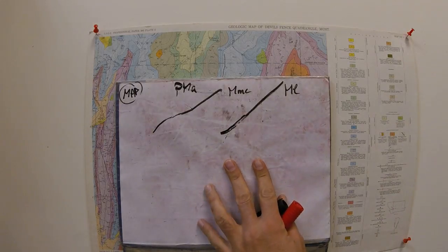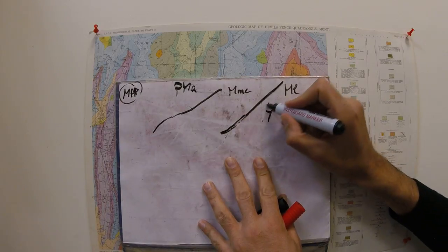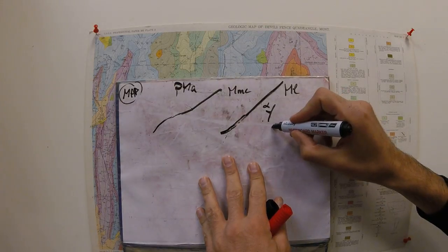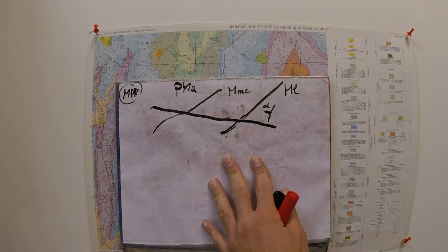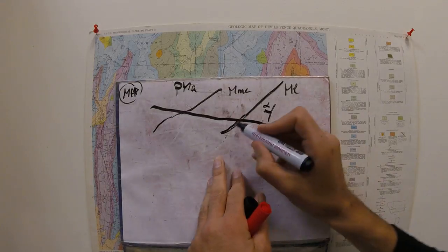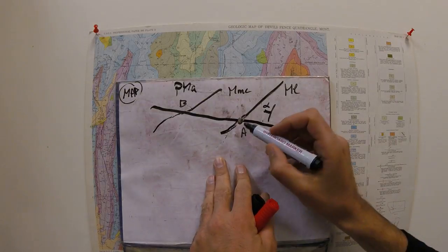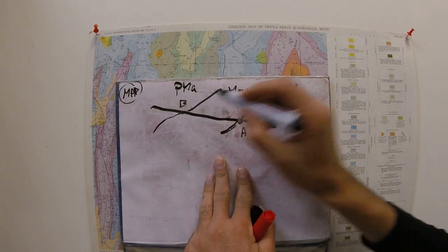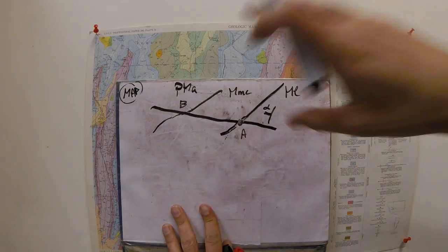So let's imagine that we are in that situation, and for example we would have a dip at an angle alpha in that direction. What we will do is draw a cross section parallel to the dip direction. It's very important to have that, because the dip angle is the value we're going to use to constrain our thickness. Along your line of section, you're going to have a couple of points, A and B, A being the bottom of the bed and B being the top. This is a map view, so we are looking at this from above.